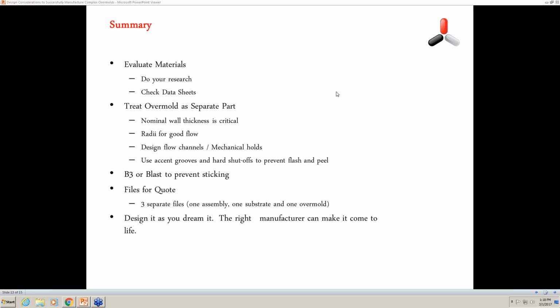If you're talking rubber materials, a lot of them will specifically say what the materials would adhere to. It'll say good bonding for PBTs, nylons, and list out the materials they have good adhesion to, but that's not always the case. So the best thing would probably be to contact the materials house, and they'll let you know if it's a good material for overmolding.